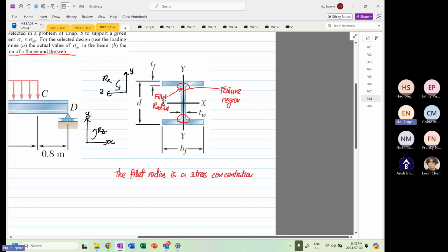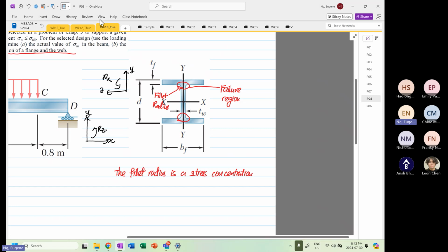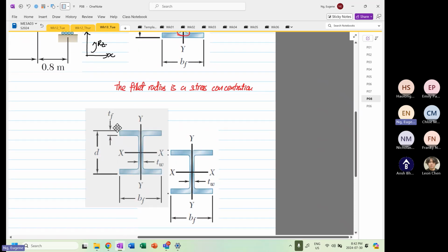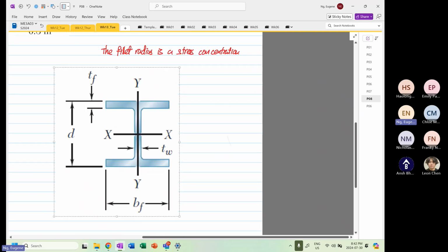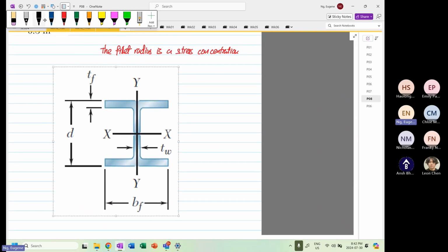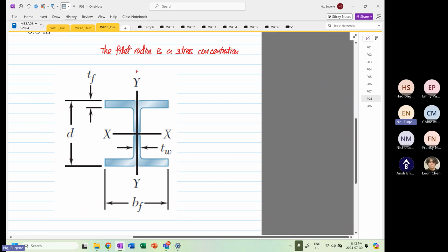We know that this is a thin wall. All the flange is thin wall analysis. So I'm going to copy this and sketch the shear flow. We have a loading applied from the top, so this is Vy, and we know that this is flowing this way.